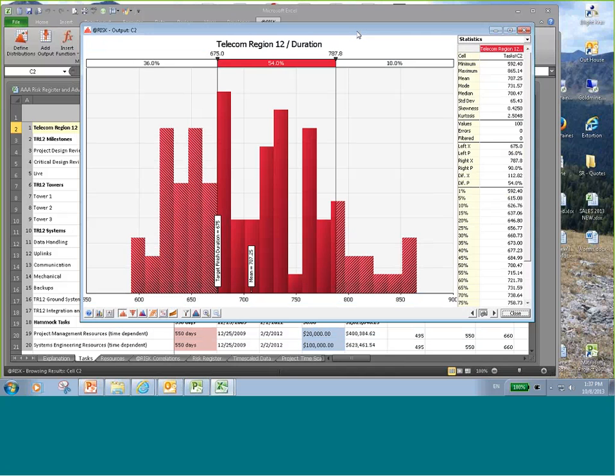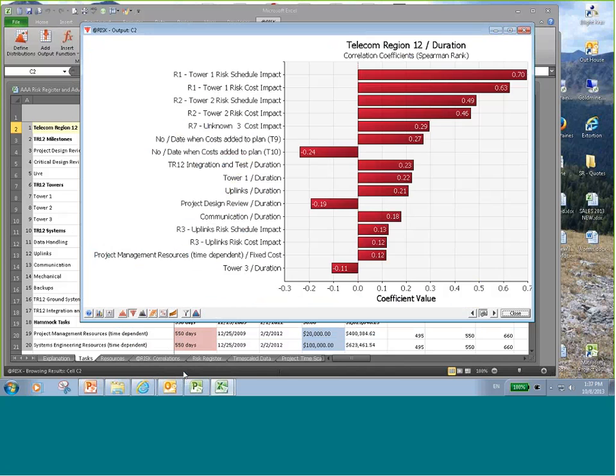With Monte Carlo simulation, we've collected a lot of data, and now it's at our fingertips. So I'm going to click on this little button right here. It provides us a sensitivity analysis. We have 5 different types to choose from. I personally like this one best. I find it easiest to interpret. So I'm going to click here, and it provides us a tornado diagram. And the values are expressed as coefficients. Coefficients will always go between -1 and +1.